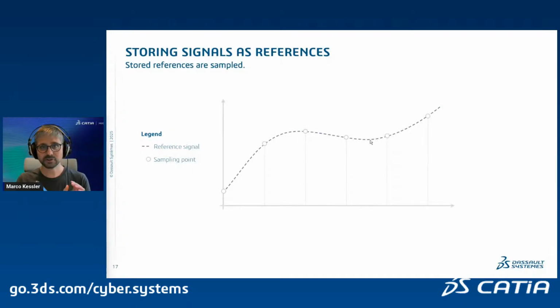And now I want to explain to you why I don't recommend the continuous recorders anymore. So what happens if you have your reference trajectory and you make a recording, you store a limited amount of data points to a file. So even though the variable is continuous during simulation, you cannot store everything to the hard disk.